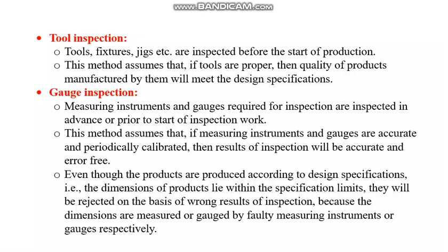All these measuring instruments should be calibrated, because over a certain period of time, because of use, some errors may creep into the measurement. Sometimes there is wear and tear, or some play comes, so they won't measure accurately. So you have to go for calibration.